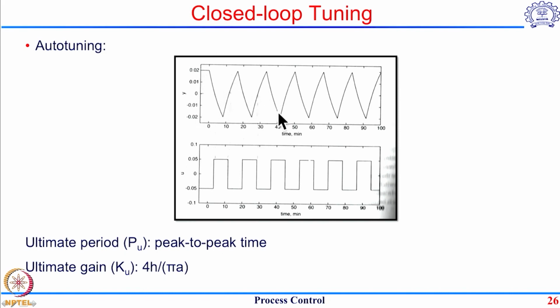It is not entirely an oscillation like you would see for a typical auto method which you had seen earlier using a proportional controller, but this type of response also gives you some relationship between the magnitude of input change and the magnitude of output change, which will give you the gain.